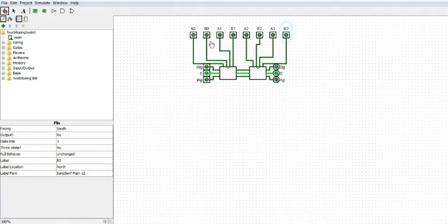So in all the parts your LSBs are equal, but in the MSB we have one bit as 1 in B, then B is greater. So likewise we can build an n-stage comparator also. So we have a ready-made IC with a 4-bit comparator. What we are seeing here in Logisim, the same IC is readily available. The IC number is 7485. It's a 4-bit magnitude comparator.